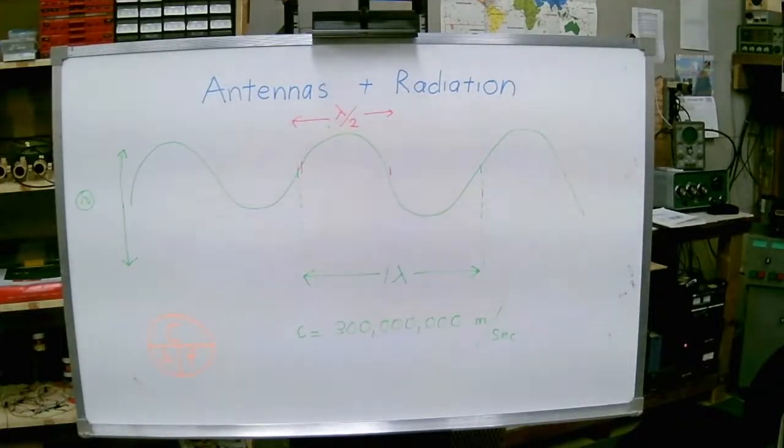Remember what we had to do to get the bias right? And we want our signal to not affect that at all. So we want to pass the AC from the signal, which is what we want to amplify, without messing up the DC voltages. Okay. And so why are we using a resistor there usually?